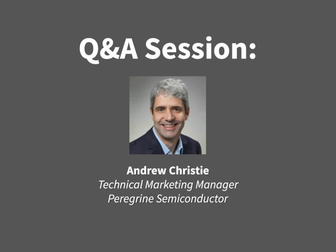Okay, great. We have another question from someone named Bob. He wants to know, what semiconductor technology is this in? So all of Peregrine's products are in a proprietary SOI process. We have a number of different versions of this. Some of these are silicon on insulator, some of them are silicon on sapphire. It's a CMOS process running on these substrates.